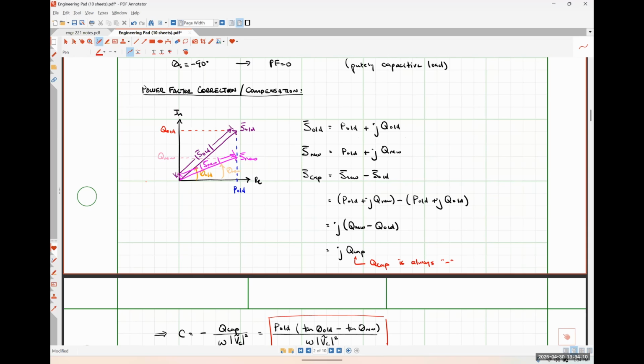For the capacitive load side of things, it's either relays that are literally just switching in discrete value capacitors, much like we would simply think about. So like, hey, I need X amount of VARs injected into my system, so I switch on whichever capacitors bring me closest to that particular value.